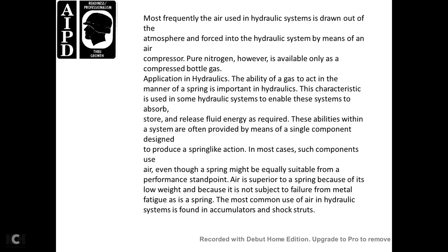Application of the hydraulic. The ability of the gas to act as a spring is important in the hydraulic system. The characteristic enables the system to absorb, store, and release the fluid energy required. These abilities are often provided by means of a single component designed to produce a spring-like action. In most cases, such components use air, even though a spring might be equally suitable from a performance standpoint. Air is superior to a spring because it is not subject to the failure of metal fatigue as a spring is. The most common use of air in hydraulics is found in accumulators and shock struts.